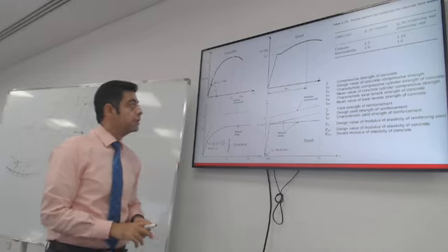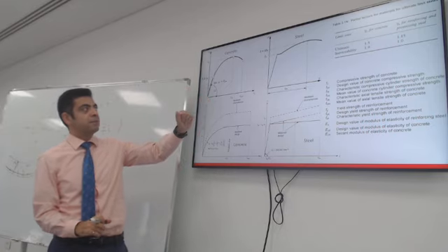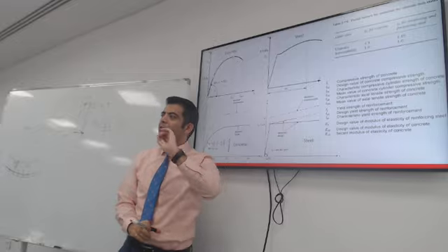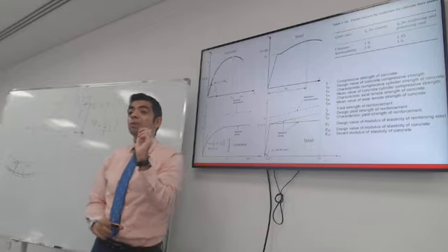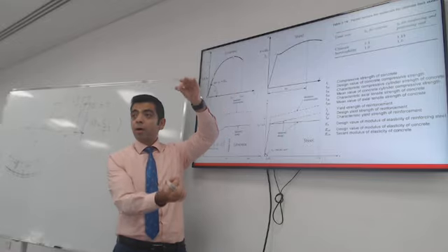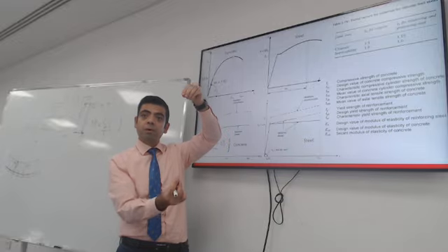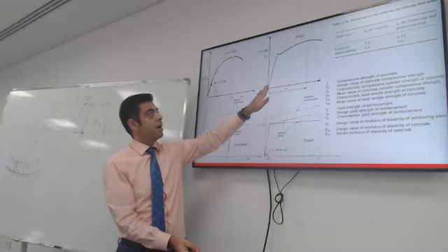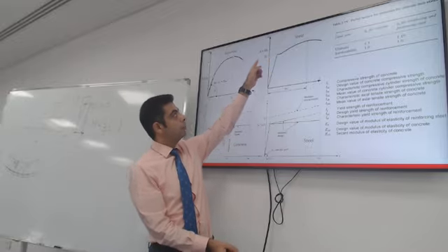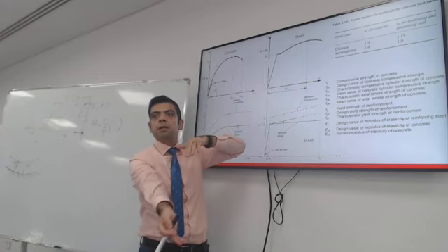You are probably familiar with the stress strain curves for both concrete and steel. The left side is for concrete, the right hand side for steel. These graphs represent the relationship between two things: the stress on a bar of steel and the strain, or like the elongation, how much it will increase in length. This is the typical stress strain curve for steel. It will go linear up to pretty much yield, and then it will have significant elongation.